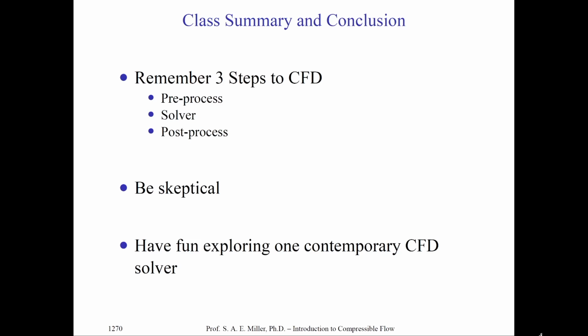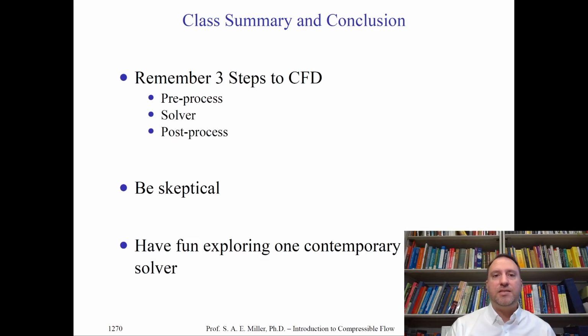So remember, this is a crash course and overview of CFD. If these subjects seem interesting to you, of course you can go on and take CFD classes at the graduate school or introductory electives, which I sometimes teach here at the university. Remember, CFD consists of 3 basic steps: the pre-processing phase, which sets up the problem, the solver, which solves the discretized equations with appropriate boundary conditions on the grid, and the post-process, which finds derived quantities as part of the design and research process.